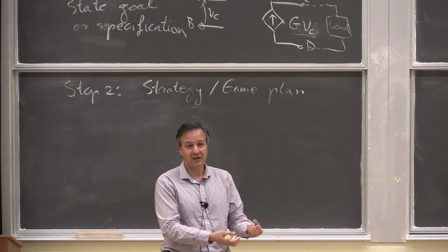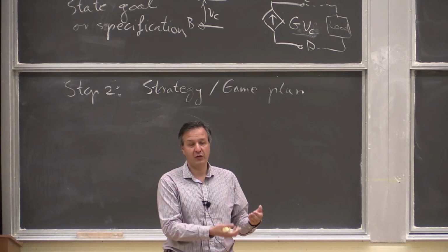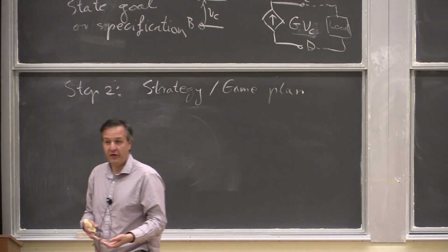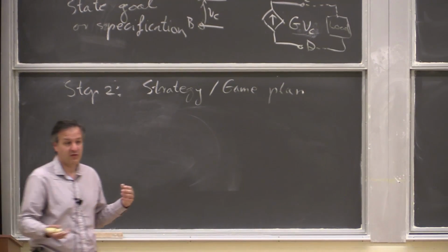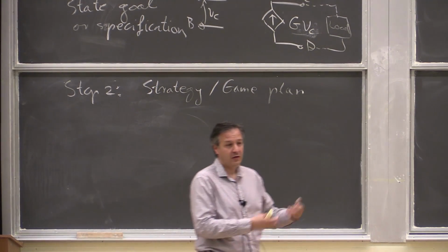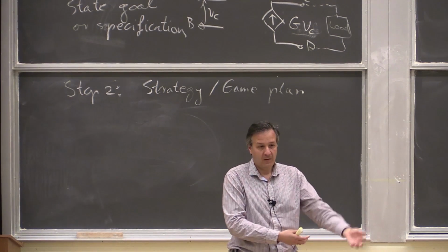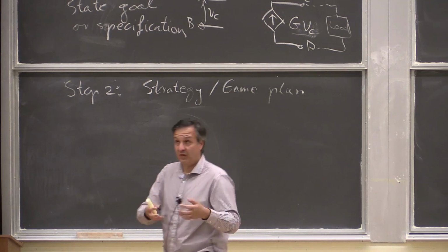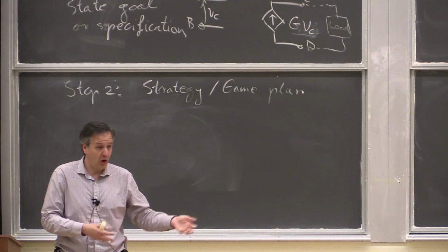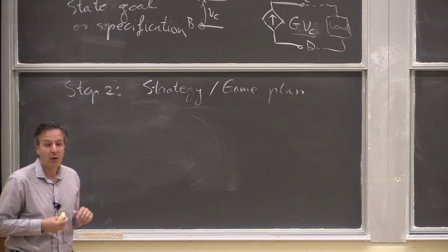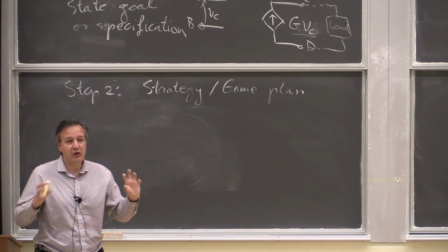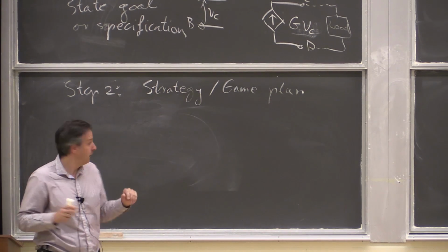That was our fundamental equation, and from it we understood that we can measure a variable capacitor, turn it into variable charge on a fixed voltage, and then later take a fixed change in charge on a known capacitor, turn it into a change in voltage, right? So that was the game plan, just based on that Q equals CV type equation, right?